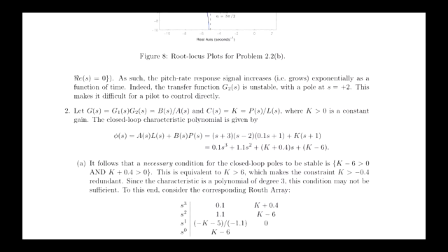So if we just have a constant gain controller, remember this is our notation for the ratio of two polynomials that defines the transfer function. So when it's a constant gain k here, we're saying P is equal to k and L is equal to 1. If you like, you could say P was equal to 1 and L is equal to 1 on k. It doesn't really matter. And we have our plant transfer function as the ratio of two polynomials B and A.